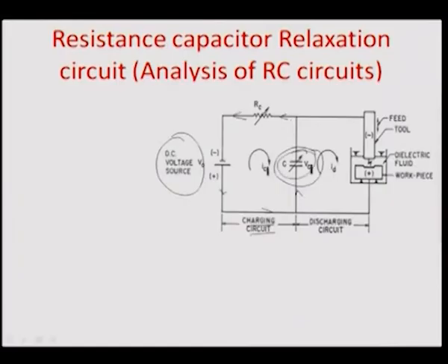Because, as you know, a capacitor is an open circuit to DC, typically this side of the capacitor would get positively charged and this would get negatively charged, and there is a huge charge containment inside this capacitor. Now, if we assume the other part of the circuit, that is the discharging circuit, to have the tool electrode combination, so this is the workpiece, this is the tool, and there is a dielectric fluid in between, typically this is what the EDM setup would look like.